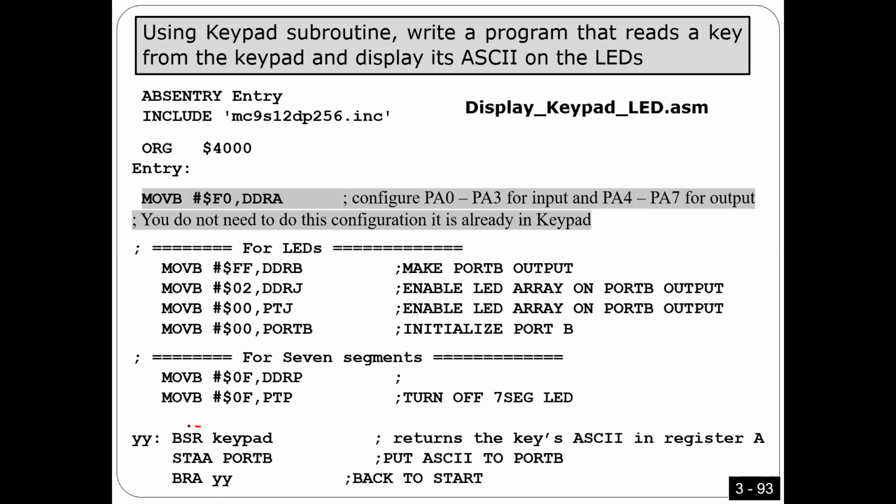That is true because you used the branch subroutine, and as I said before, branch subroutine only works if keypad is short. It may be okay in this program because this is a small program. However, in your program, it's a long program, and that's why it gives you an error, because it's not short. What you have to do is say jump subroutine instead of branch subroutine. If you do that, you're not going to have this problem. Okay, guys, is that clear? That makes sense. Yeah, thank you. So try jump subroutine and see. I think you should be okay because it should be a long branch.